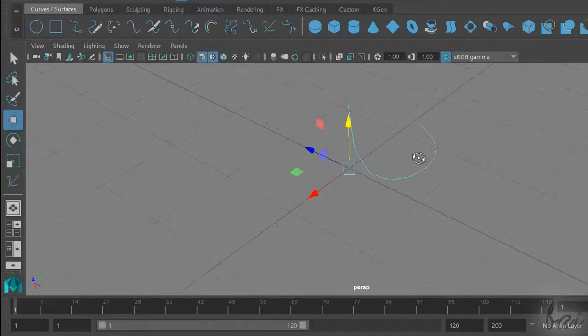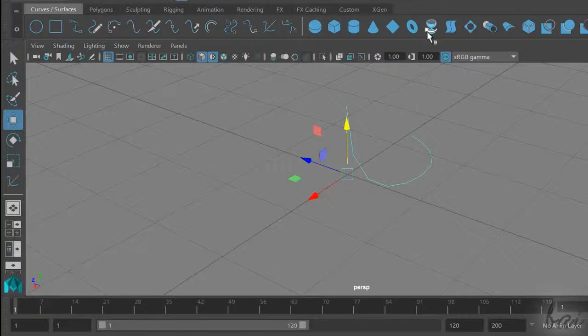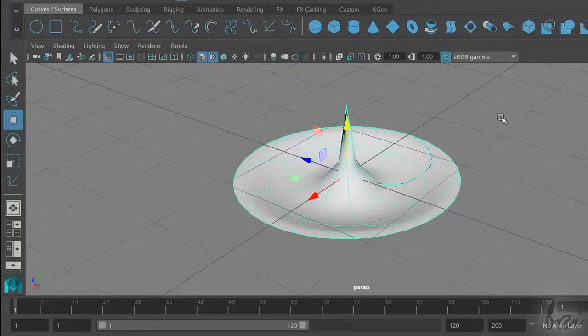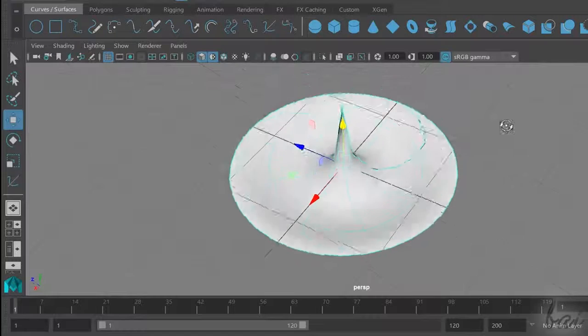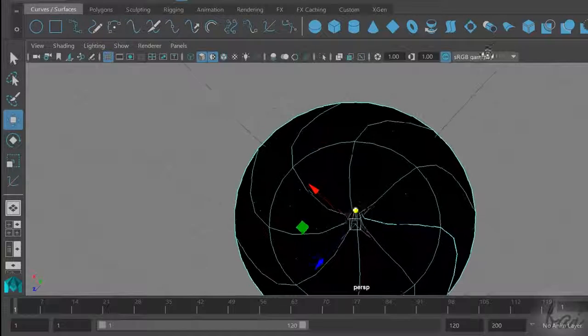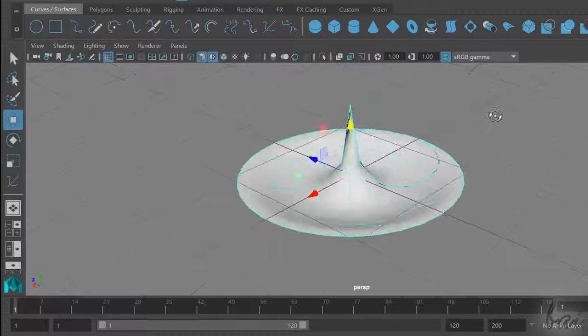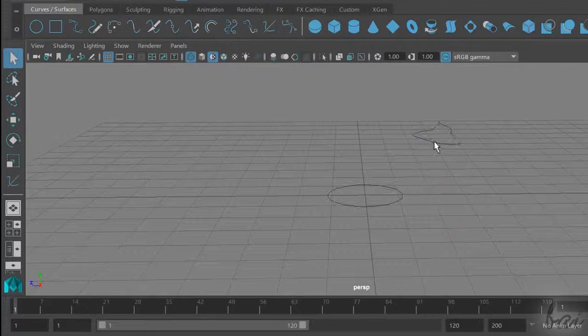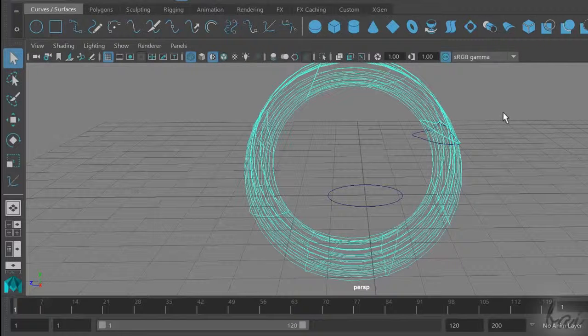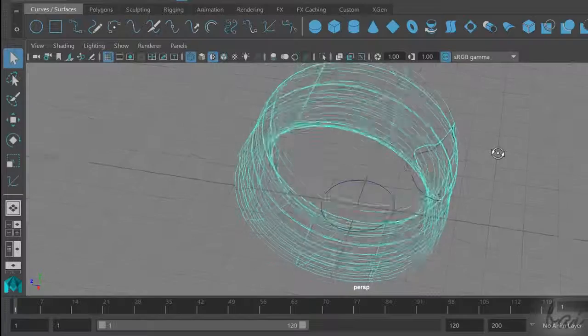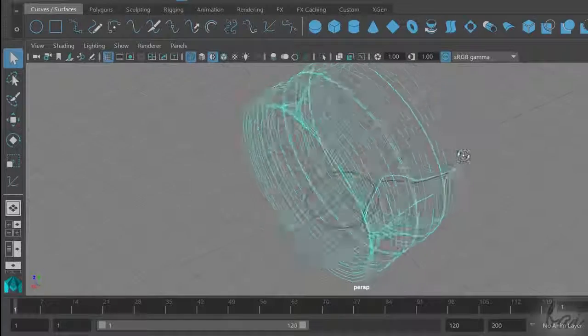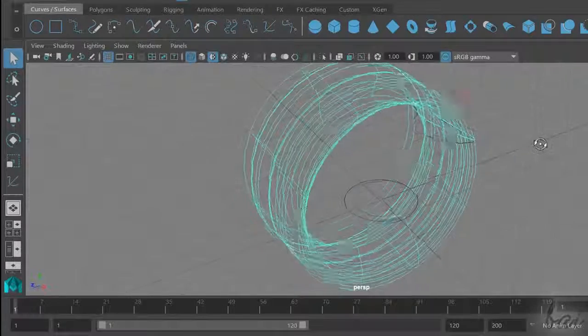For example, if you have a curve spreading on the y-axis, you can use Revolve to create a 3D surface by rotating it around the y-axis of the system, or use the Extrude tool to create a 3D surface from a closed curve taken as a path and a second curve taken as section. Remember to select the curves before enabling the tool.